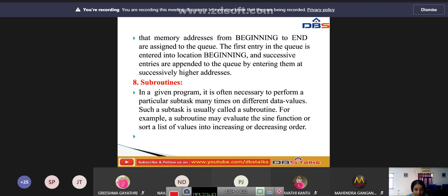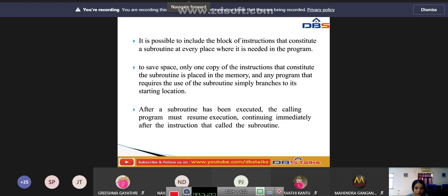So whatever program we have taken, the program branches to a subroutine. We say that it is calling the subroutine. The instruction that performs the branch operation is named the call instruction. In the subroutine, we return to the program that called it by executing the return instruction.